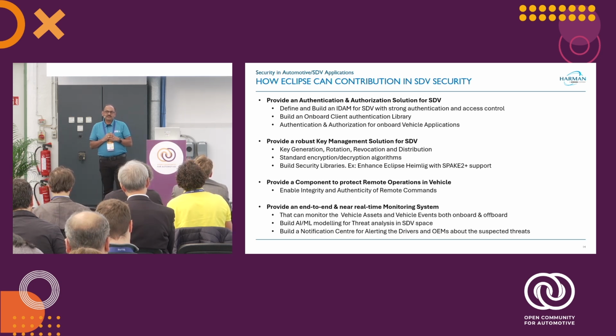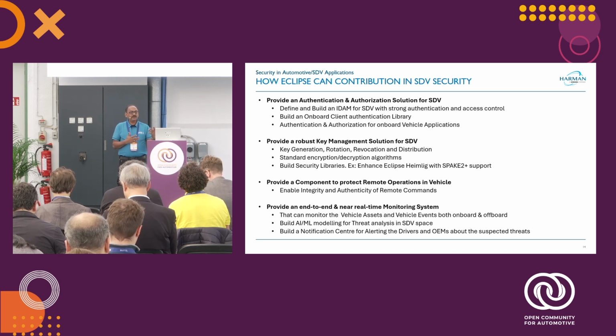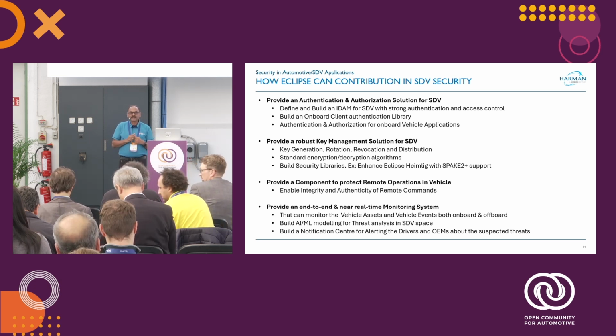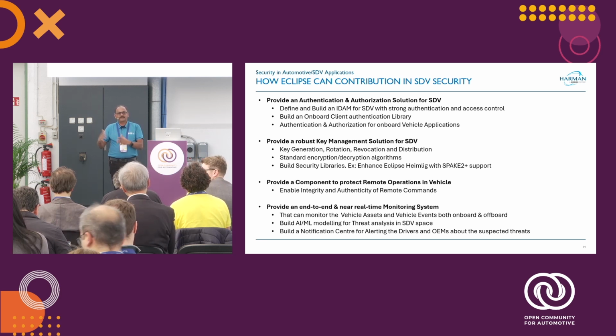Okay. So actually, TARA is still one of the best practices that we follow when we are trying to build automotive systems. During TARA itself, you can identify the different use cases and the recommended algorithms, or whether they are already following them. Otherwise, you can come up with the list of cryptographic algorithms based on the TARA analysis that you have. And the TARA analysis, yes, definitely it will continue as is. I'm not even sure whether it is different for SDV or normal automotive products.